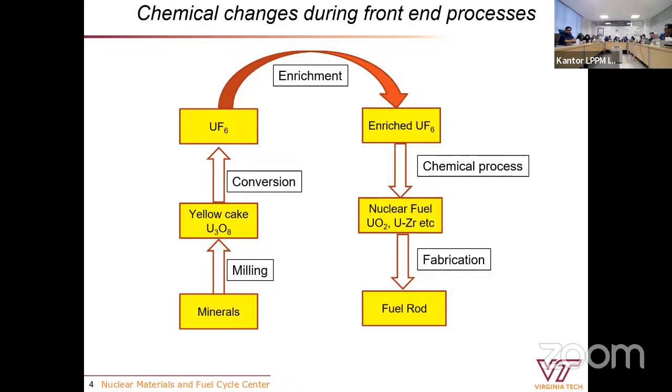And our experiments show that for your graphite at 10 bar or 5 bar pressure, the salt can completely pass through the graphite. That's an issue, a big issue. We do not want the salt penetrating the graphite. But unfortunately, we cannot make the graphite always have porosity.